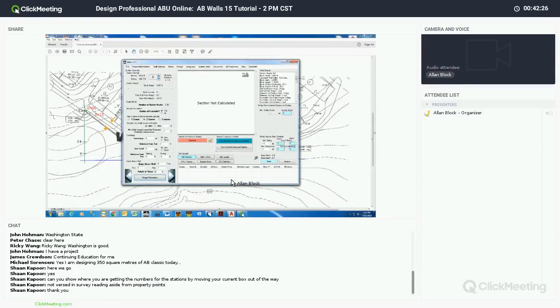All right, to start us off, I'll just take us a tour down the left-hand side for all of our action areas, so that way we know what we're going to do. Starting off in the top left, we have a section geometry section, number of section 6. This is telling us, based off of the heights of our wall, the software has determined that section 6 is our tallest section, so we're going to use that as a starting point and move from there. So that way we hopefully have less modifications to make on the smaller sections.